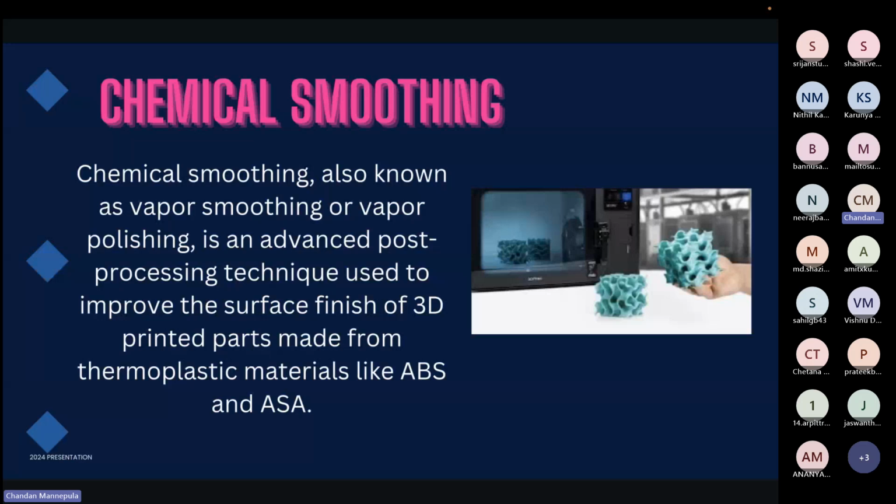Then what is meant by thermoplastic materials? What is the difference between thermoplastic and thermosetting? When a material is cured, thermosetting materials strengthen and form chemical bonds within themselves, while thermoplastics do not form any chemical bonds while curing.